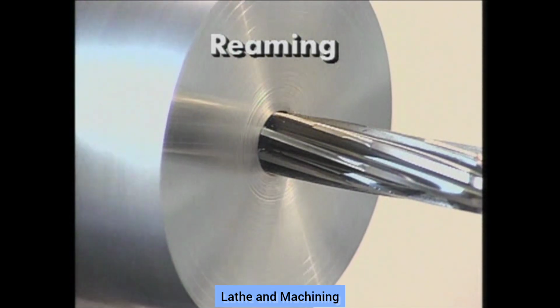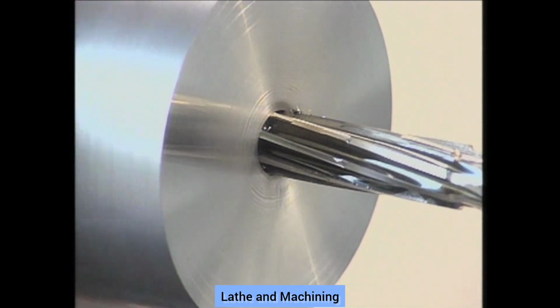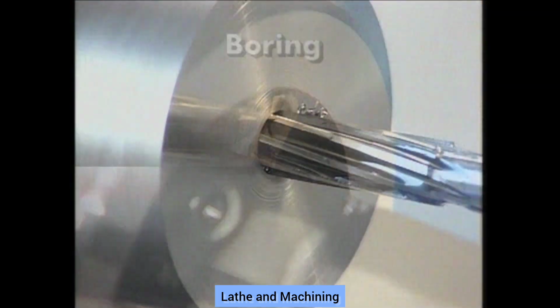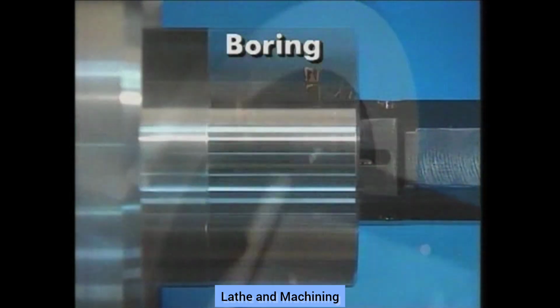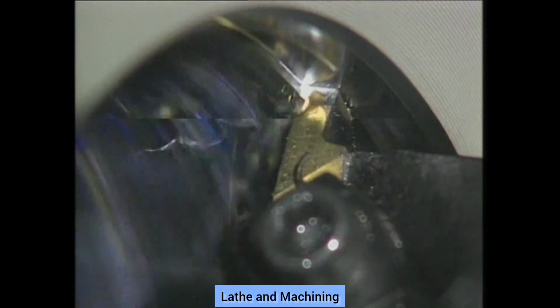Reaming enlarges and finishes a previously drilled hole by removing a small amount of material with a rotating fluted tool of the desired hole diameter. Boring enlarges and finishes a hole with a single point cutting tool, like a turning tool. The boring bar moves along the axis of the part, as in turning, but inside the drilled hole.